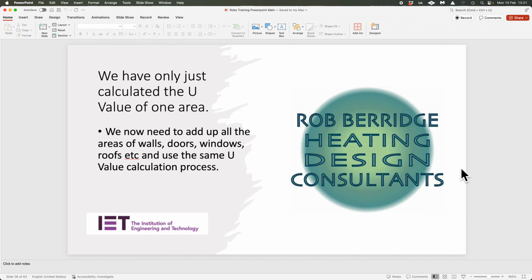We're looking for a nice low U value for our heat losses, and all we're trying to do as heating engineers is replace the heat that is being lost constantly out of that building fabric, at whatever the outside temperature is, to maintain our indoor set point. So very, very simple. Look at it methodically and logically as you design these or calculate these U values.